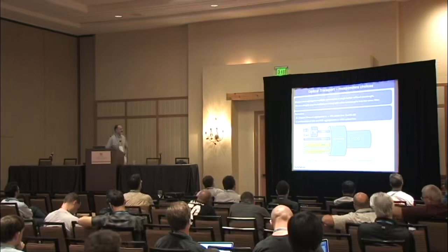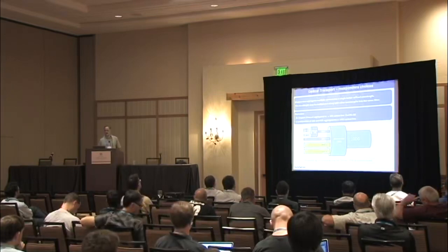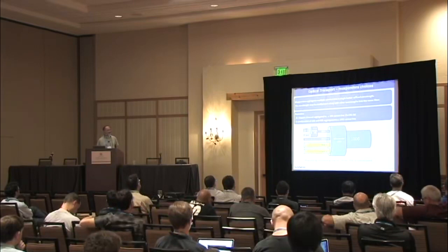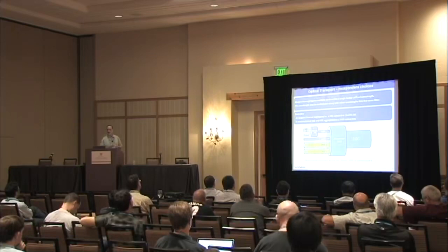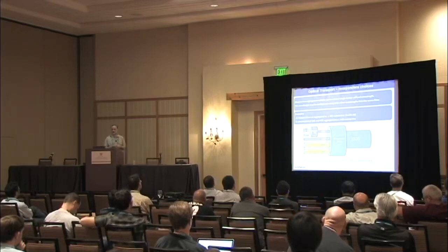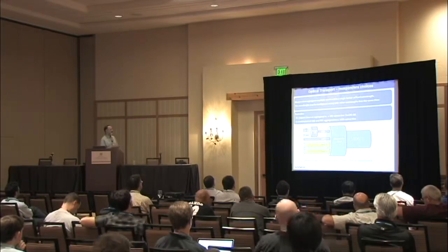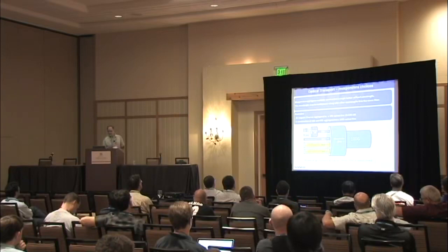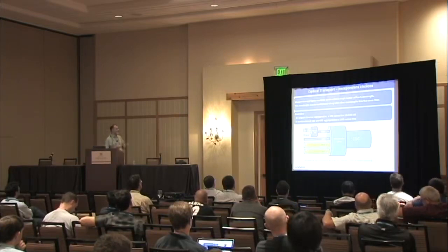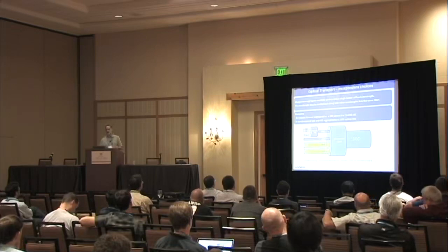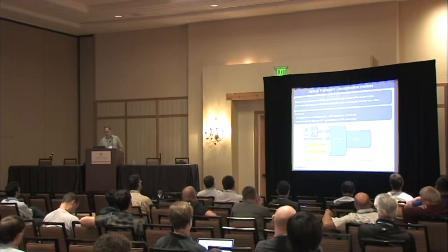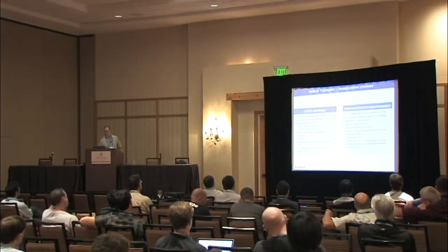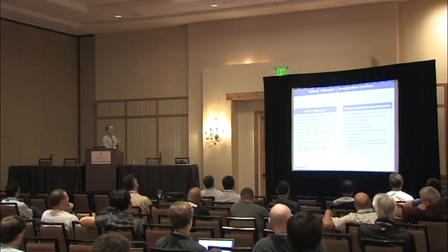Maxponders, as you guys know, aggregate multiple services into a single better utilized wavelength. And that wavelength then goes over the WDM, through the WDM multiplexing scheme and goes on the fiber. Typical example, take an 8 gigabit Ethernet aggregated to a 10 gig optical line. And if you want to go next in line, you basically can combine the 10 gig Ethernet with some 40 gig, generate a 100 gig line, but that's the idea. You can have basically TDM or OTN based and packet based. And the idea is pretty similar.